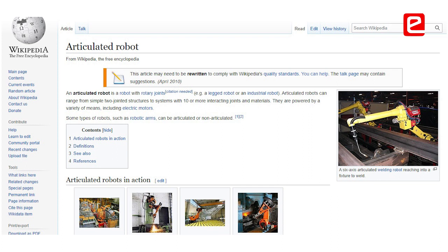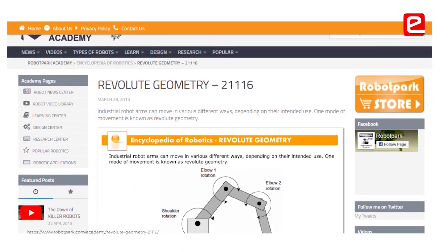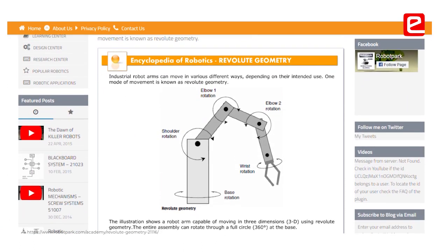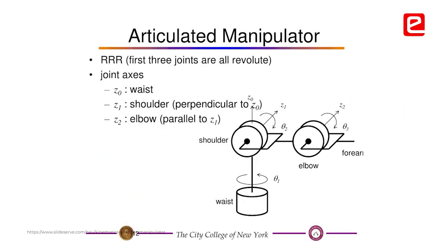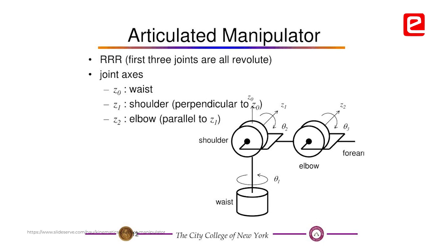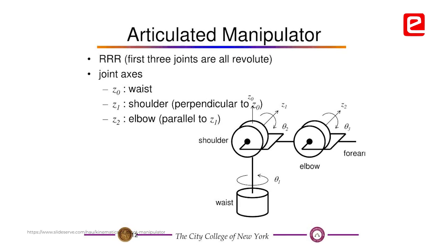How did you choose this robot? Basically, what were the design considerations for the robotic arm? The reason for choosing an articulated manipulator was that it consists of all revolute joints. So if we want to realize this manipulator in real life, the transition from simulation to actual hardware would be easier, and the constraints coming in terms of friction identification for the real hardware and making computed torque control or some kind of impedance controllers for the robotic arm. These issues would be easily tackled in actual hardware if we have a revolute joint instead of a prismatic joint.